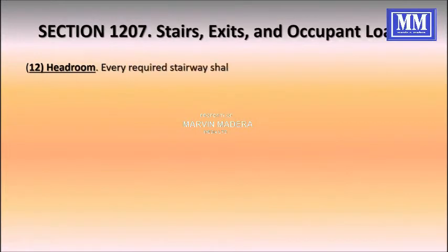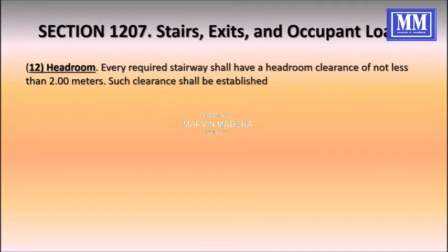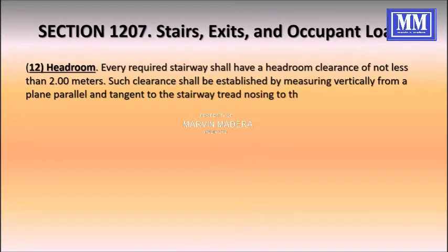Headrooms. Every required stairway shall have a headroom clearance of not less than 2 meters. Such clearance shall be established by measuring vertical from a plane parallel and tangent to the stairway tread nosing to the soffit above all points.